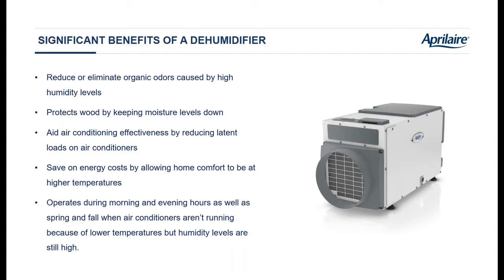Even if you have a two-stage air conditioner or a variable speed, true variable speed air conditioner, which do an excellent job dehumidifying when they're running, it still makes sense to install a dehumidifier in that home, because there's going to be lots of times when the home is the temperature that the occupants want, but the relative humidity is still too high. Think about shoulder seasons, spring and fall.